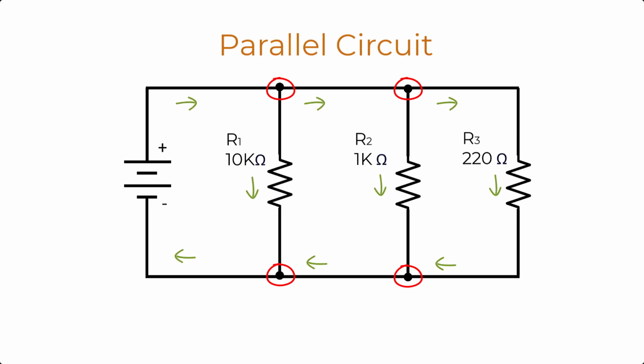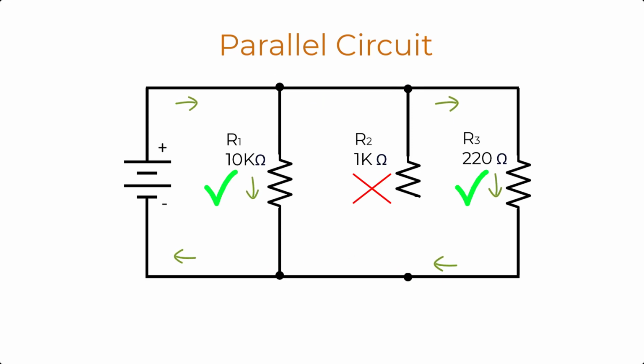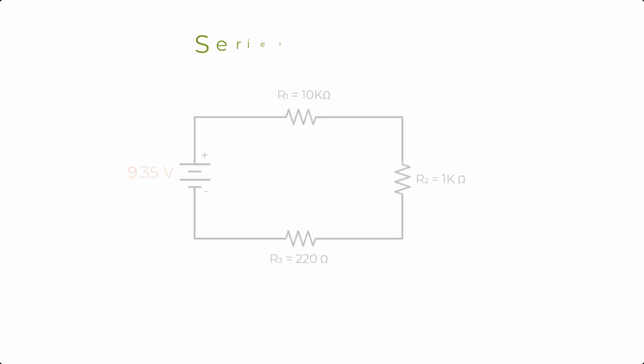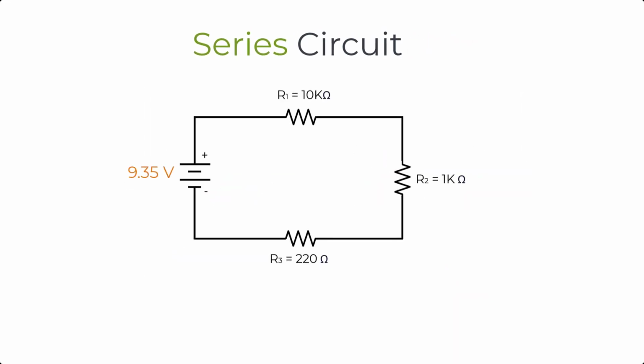So, a portion of the current is flowing through all the components at the same time, because each branch is independent of the others. If there is a break in one of the branches, it will not affect the other circuit components in the other branch. Unlike in a series circuit, wherein the components are connected in consecutive ways, one after another, creating one big loop for the current to flow. In effect, if one component is burnt, the entire series circuit is opened and cannot work.